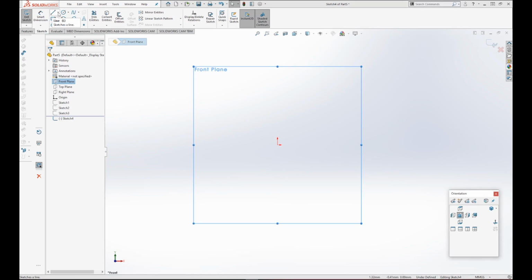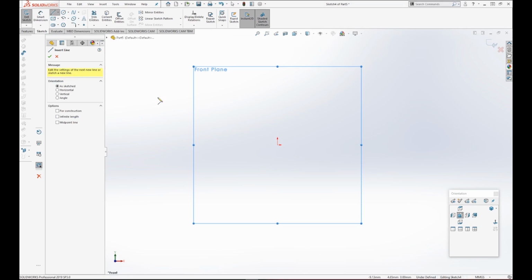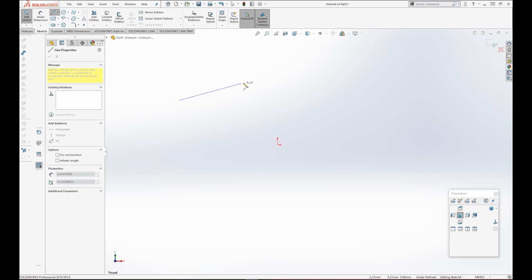And then I'm gonna show you guys this line tool right up here. So if you click the drop down menu, you're gonna see 3 different lines. Go ahead and select that very first one. Okay, so I'm gonna show you guys how to use this. Go ahead and click and then move over and click again. You can see the behavior, how SOLIDWORKS lines work here. When I finish my second click, it assumes that I want to make another line. So I'm going to go ahead and just continue clicking and closing it up.